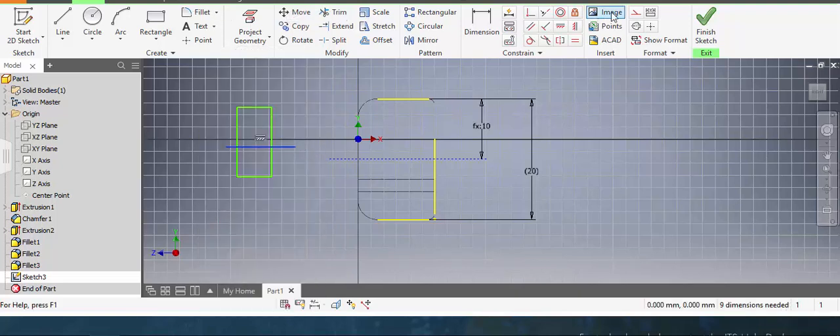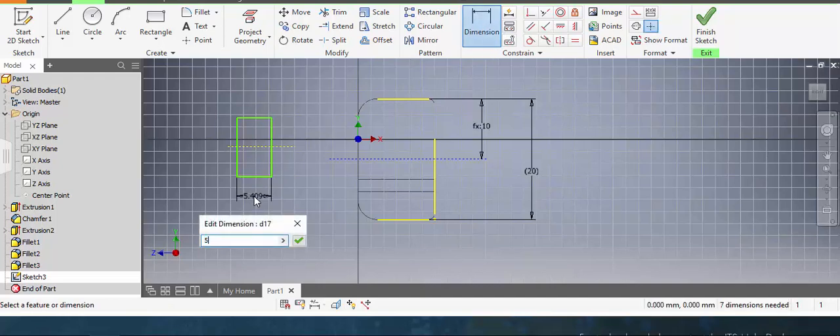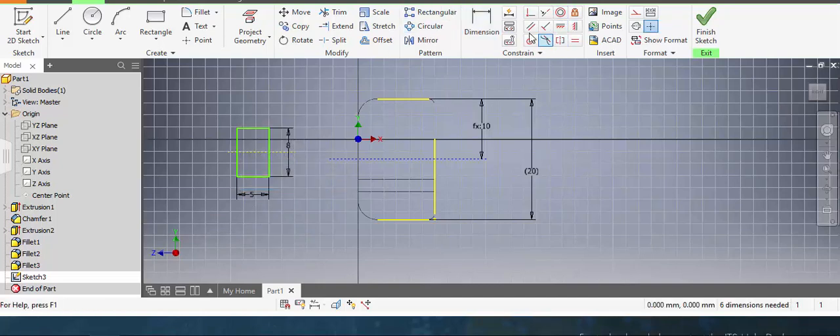Here right click is not giving me the option, so I'm picking there, and now I will say symmetry related to the middle one, and now I can constrain outside completely. So I'm adding a dimension, and later I can add location. So you see my dimension will be maybe 5, 6, and now I will use this constraint to align 2 lines together. Again, you see the same constraint is selected, coincident, and then I'm just clicking on two of these lines, and they will be in the same level.